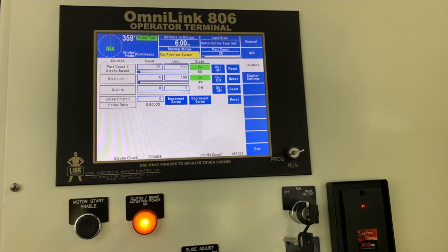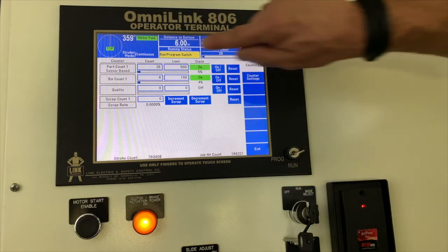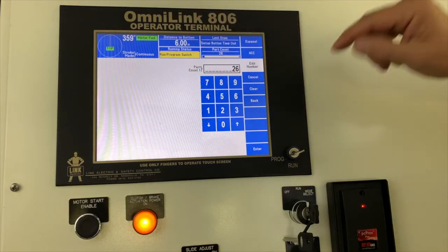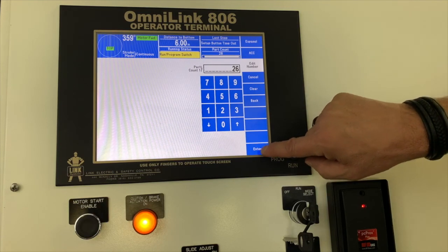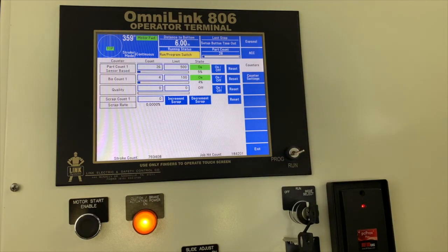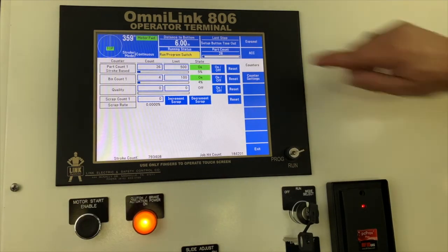If by accident you have cleared the part counter, perhaps in order to run a hot job, you can enter back the number of previously completed parts. Put the count in where it says Count. Part count is the example here. Once you arrive at the count, you will need to reset in order to continue. Confirm yes.